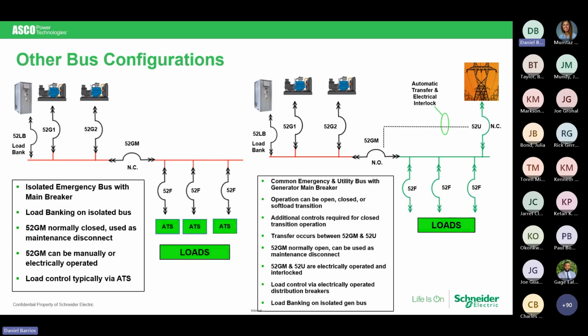What that is going to do is turn off the resistors, the portion of the load bank, which is nothing more than a big hair dryer, okay? But the thing we like to point out is that when we are discussing the load bank circuit breaker feeding the load bank, we're not going to trip it. Why, Daniel? Because we're going to turn the resistors off, but we're going to allow the ventilator fan to keep running to cool those resistors down so you don't damage one.